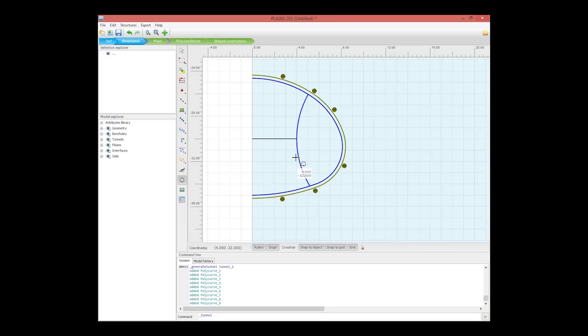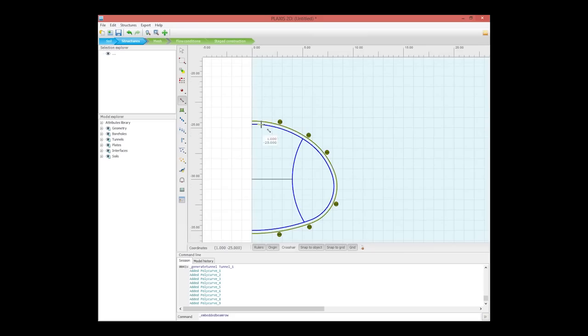So to finish with the structural element, we must now include the embedded beam, the rock bolts. So the rock bolts could be created using this command here, line, create embedded beam rope. And then we could simply select a begin point and then an end point.